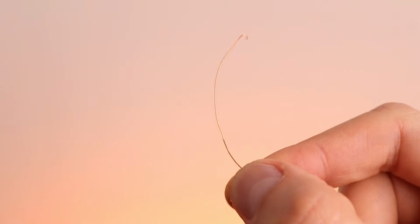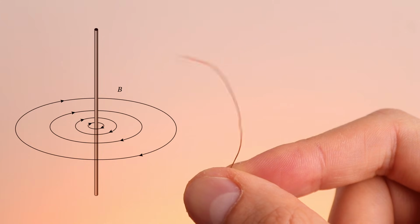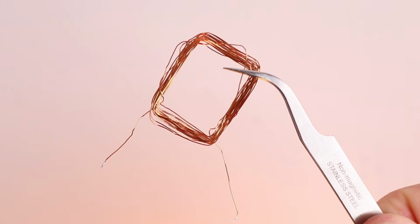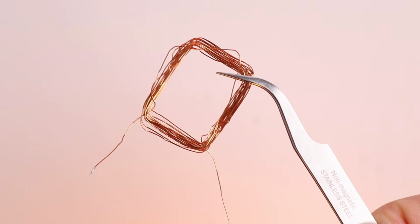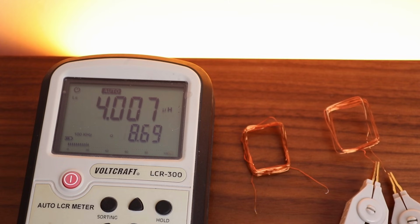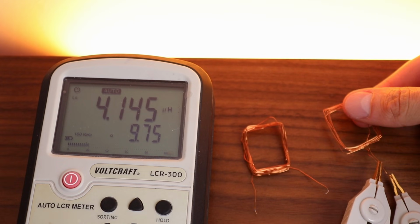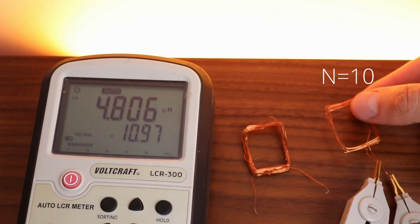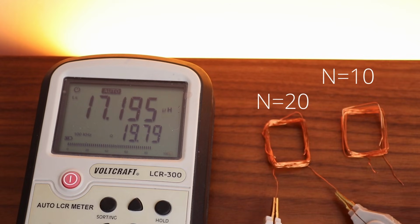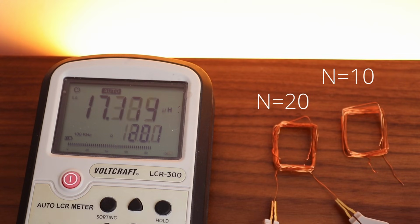The problem is that the inductance of a single piece of metal is usually too low to be useful. That's why inductors are made with lots of copper turns. Each turn contributes to the magnetic field, making it stronger. Let's take an example. Here I have 10 turns of copper with some inductance. Now I add 10 more turns and measure it again. The inductance increases by about 4 times.